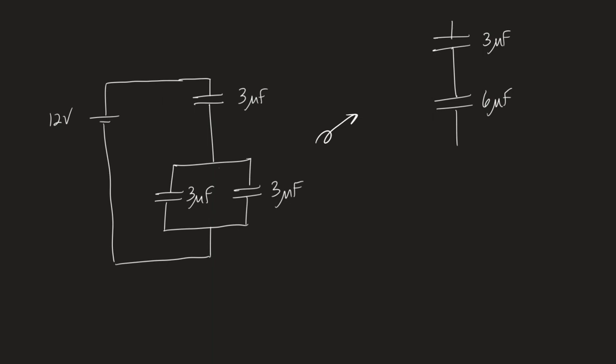But now I have a system that clearly is pure series capacitors. So I start from here and get down to a single capacitance. I'm going to have to use the rules for series to do so. And we just did this one, so I don't think I have to go back through 1 over 3 plus 1 over 6 equals 1 over 2, and then invert the microfarads.